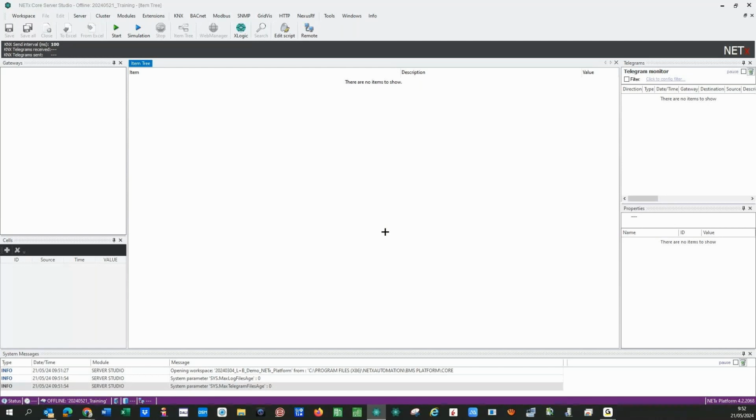We will have devices, and we will have data points mapped inside these devices. The way to integrate the different protocols will be different because the protocols are always different. For example, Modbus is totally manual. It's a vendor-specific protocol. So every single vendor, every single manufacturer will do the mapping in a totally different way.